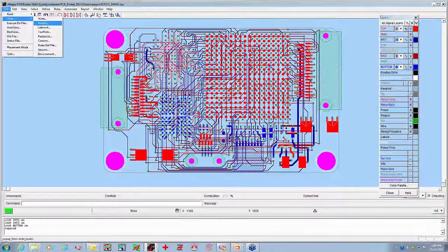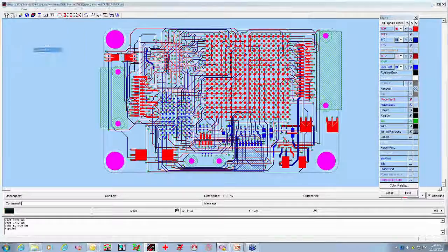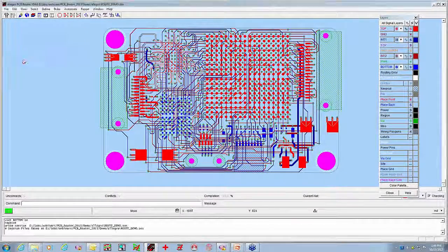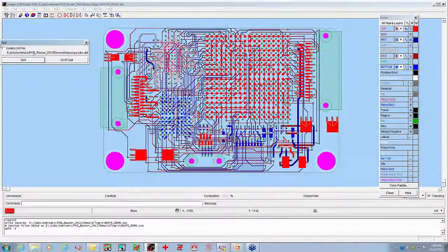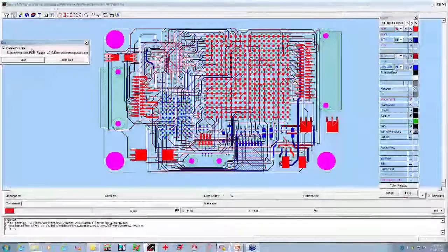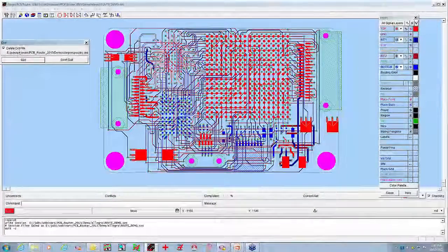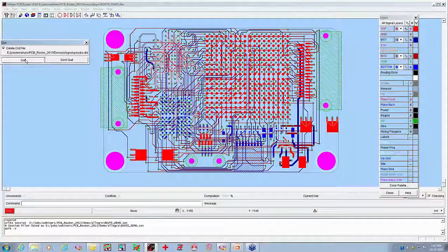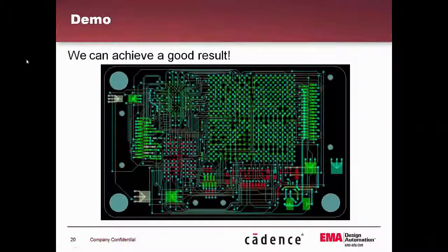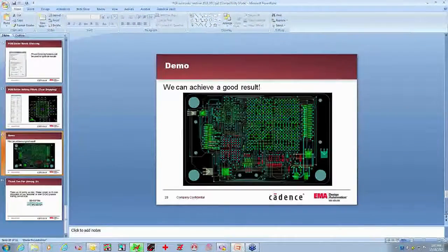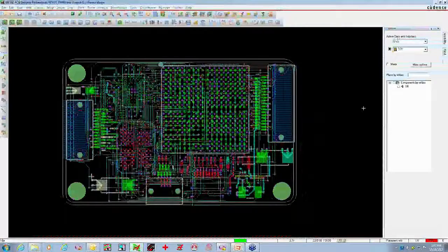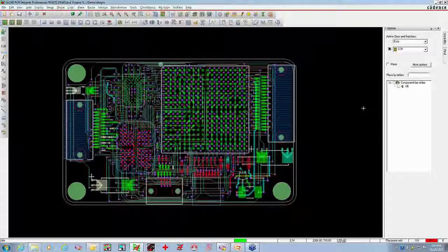I'm going to write what they call a session file. And now I'm going to exit the Autorouter. It also records whatever you did to a text file called a did file. I don't really care about that, so I'm just going to delete the did file. And if I come back now to the board, let's go back to my board. Here it's merged those results.